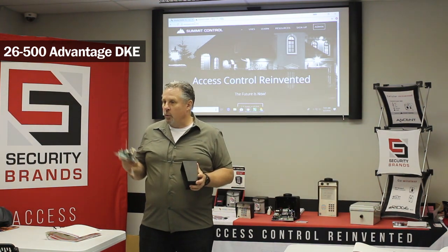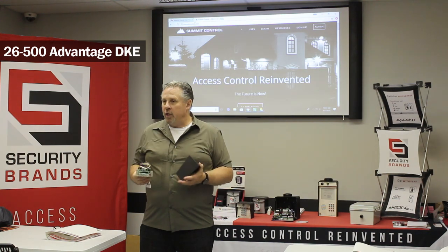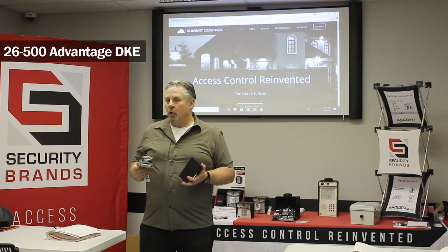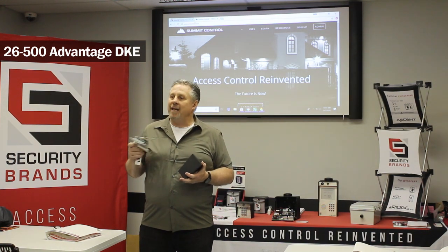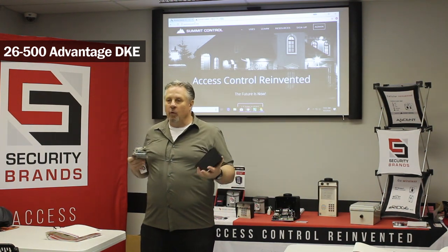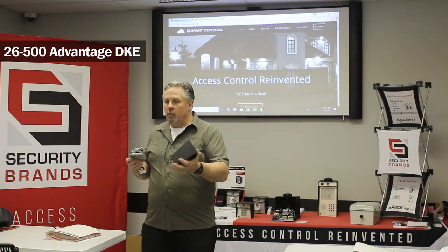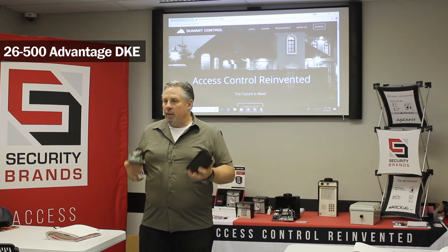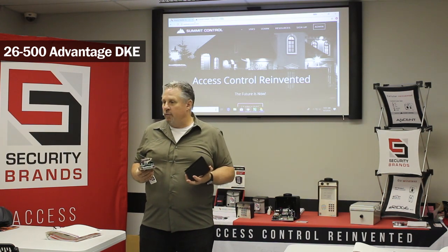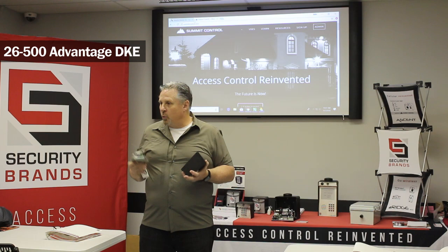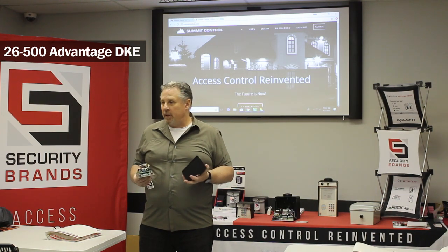We'll take the polarity either way you lay it on here, and then we change it to what we need. So it'll handle 12 to 24 volts AC or DC. So you bring over your 12 volts ground and your 12 volts positive and put it in there. You bring over your AC 24 volts, and you'll need 2 wires to go on terminals, and we step it down.